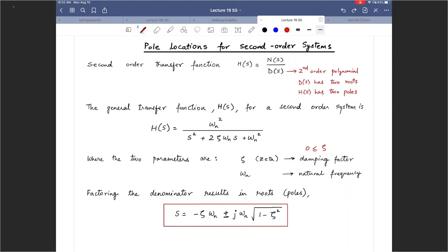Next, if you have oscillations in the response of the system, then you will have those oscillations at some frequency, right? Omega n is the natural frequency, the frequency of these oscillations if there was no damping present. But if you damp out some oscillations, then they happen at some other, lower frequency, which we are calling the damped frequency. We'll talk about that in just a bit.